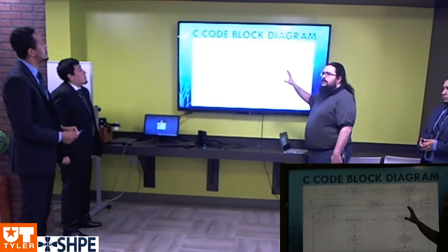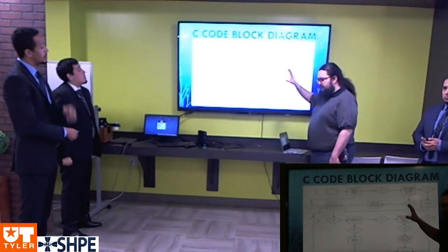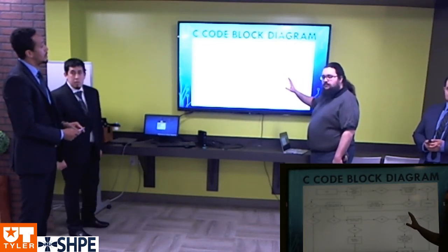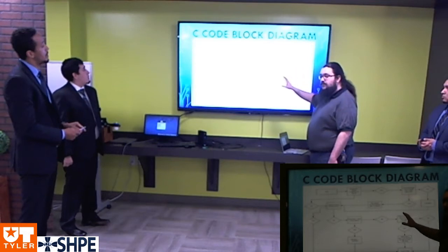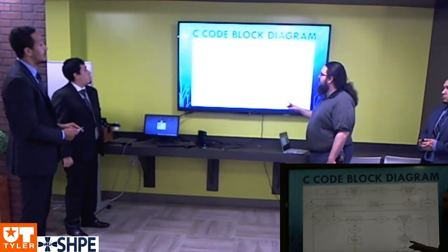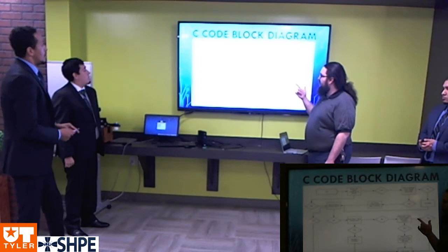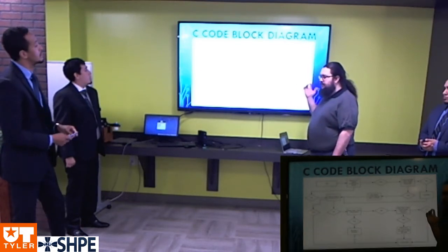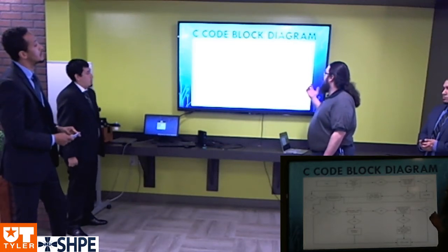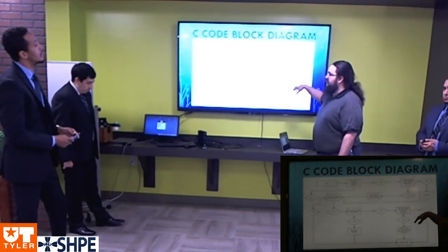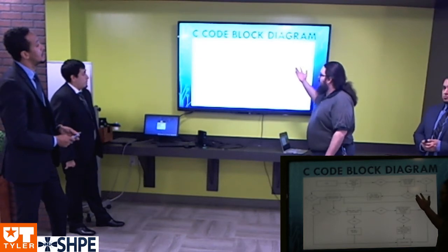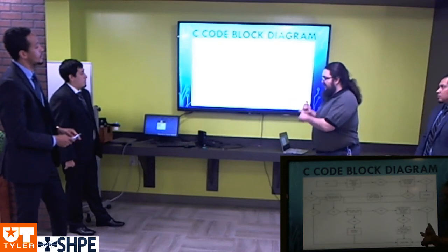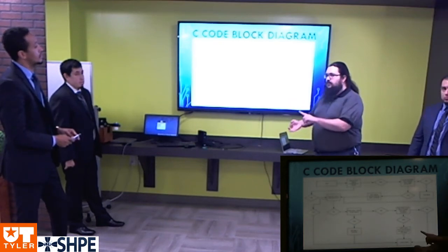Now, in terms of programming and monitoring, the Arduino uses a polling loop to check for an NFC signal, evaluate and check against its list of allowed codes, and either announce that it will lock or that it doesn't recognize the code, and proceed to unlock the door and wait for the door to be closed after a certain delay in order to relock.